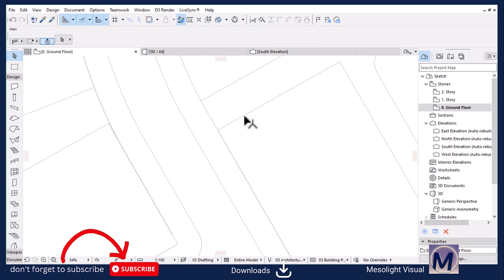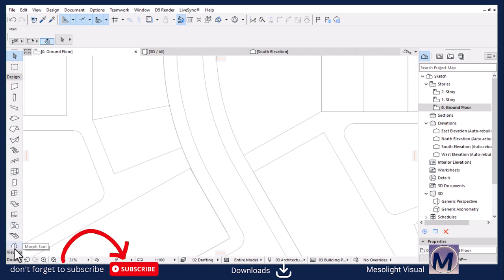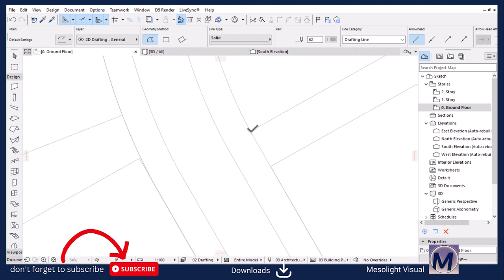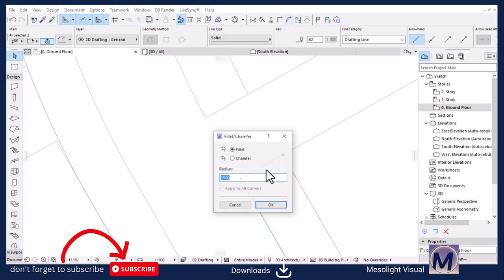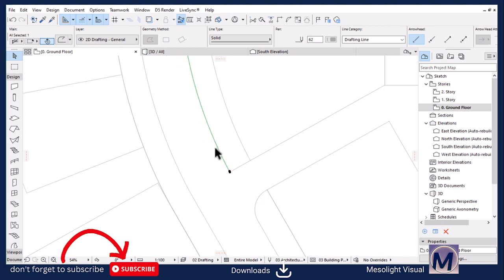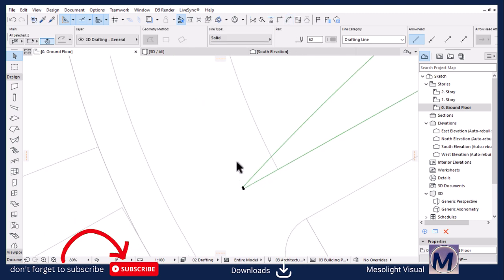I think we also have here, because this is a road, these are internal roads that are joining the main road. So I can just pick this line, pick the parameter of the line, and then I'm just going to draw just like that, and then select, let's trim, then trim, select these two, fillet by 3.5 radius. This one is going to be challenging because we have a point here, and it's a curve instead of a straight line. So if you try to fillet, it won't work. You see, that's the problem.